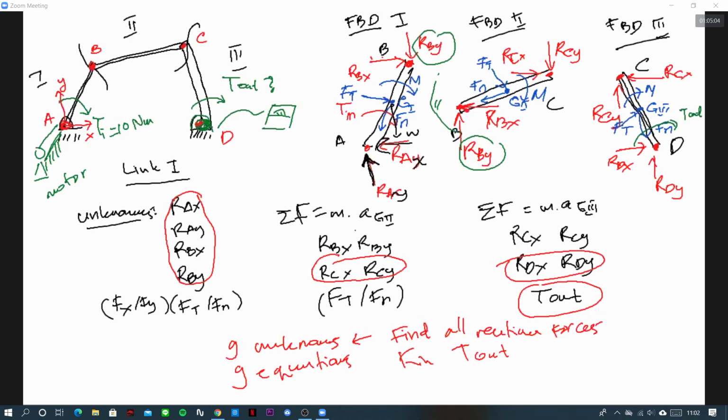Let's go to the drawing, the above drawing, because the way you are going to solve is from this coming to this and then finally here. So it means one by one for each link you will need equations. So you still need 9 equations, but you don't have to solve all values in the equations. Okay, let's try to solve first for link 1.